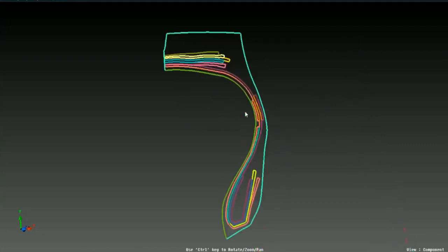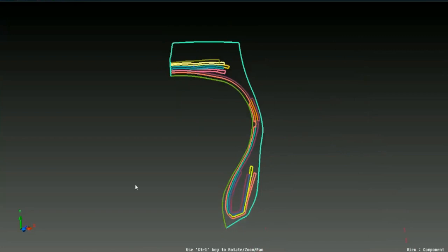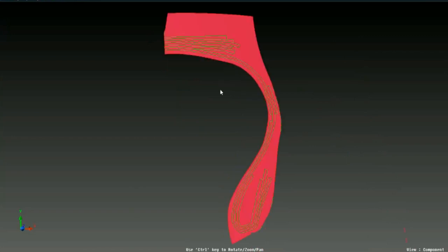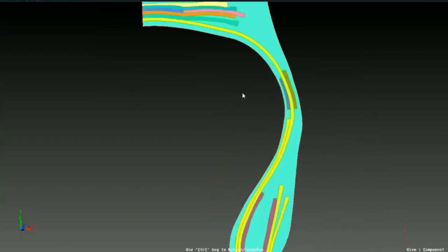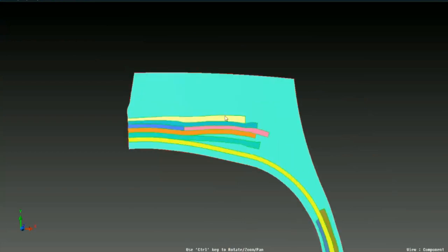Now once we get the CAD input data from the engineers, what we can do in MeshWorks is create a CAD surface and do the trimming of the curves onto the CAD surface, like what we can see here. So very nicely, it's just a one-step tool, and once the trimming has been done on the CAD surface, we'll nicely go and organize our CAD into different components. These different components are nothing but the reinforcement where we will be applying different materials and properties. And also when we do the meshing, there will be different components with respect to the reinforcement.